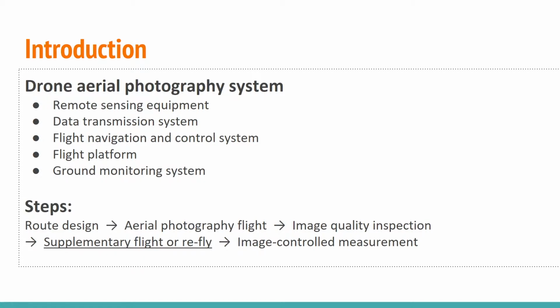And here are some steps we need to go through when using drone to get some images. Route design, aerial photography flight, image quality inspection, supplementary flight or reflight if necessary, and last but not least, image control measurement.